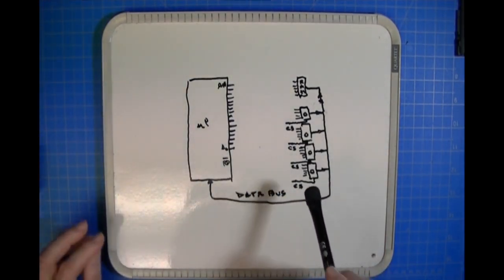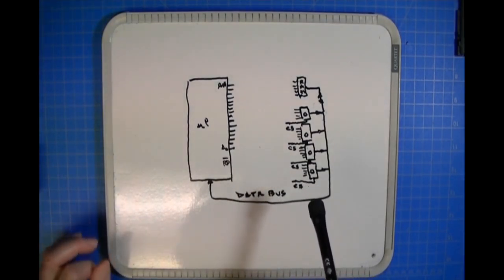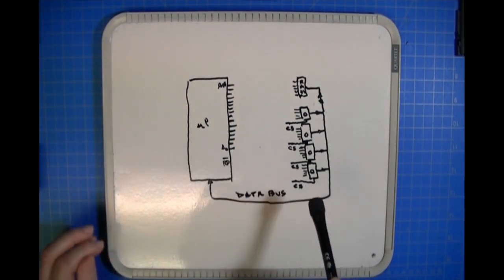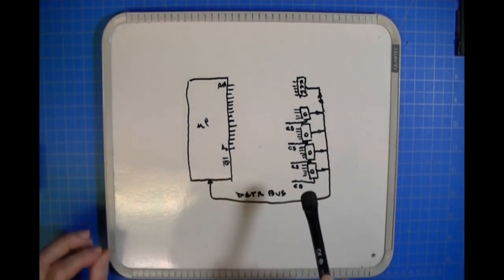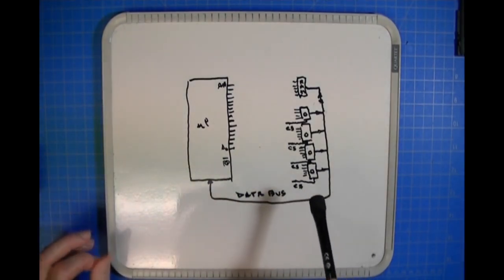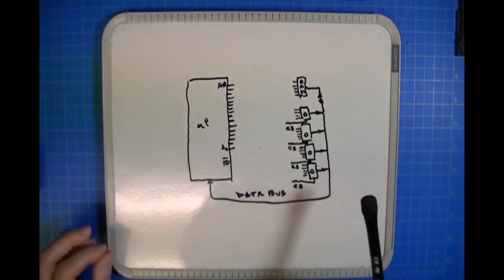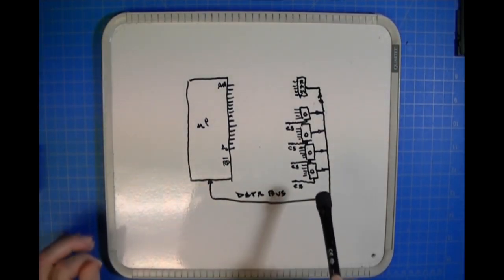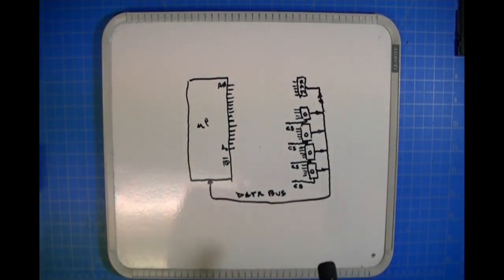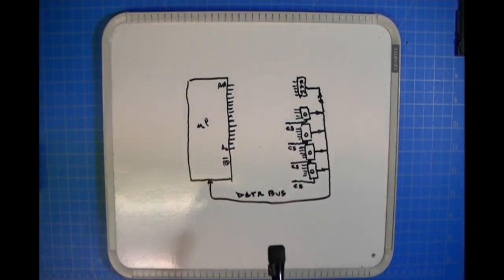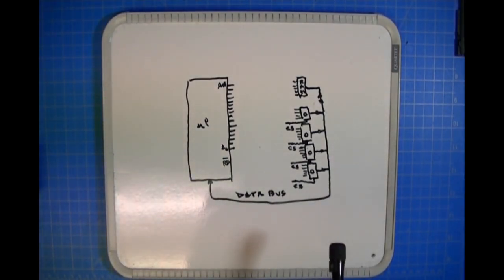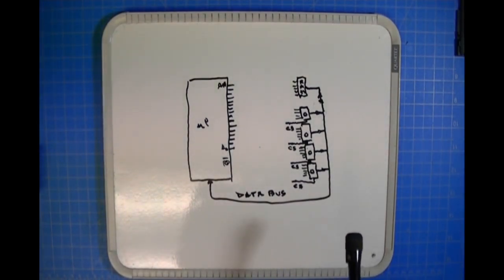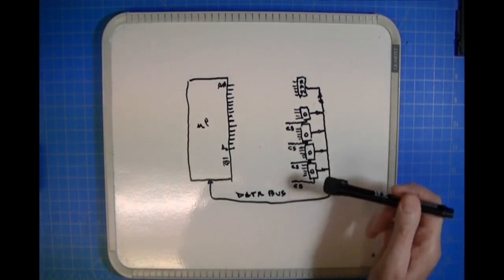Bipolar PROM, PROM, is programmable read-only memory. There is no E, and there's no E because once they're programmed, you're done. You can't erase them and reuse them. It's a one-time deal. Well, why would you need it? I'm going to try and fundamentally go through quickly how a microprocessor works with its memory. In this case, I've drawn 4 EPROMs.